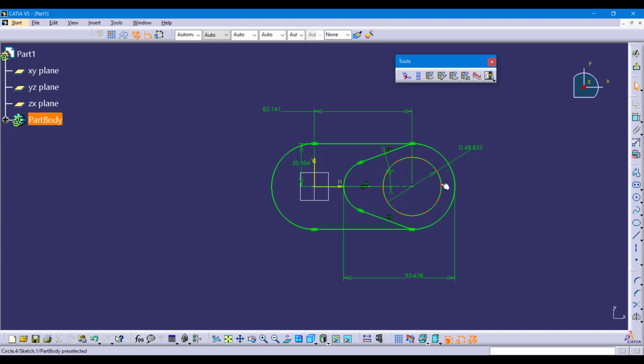The circle is a singular entity, and if you are trying to output or segment a singular entity, you are going to use the icon called Output Feature. Just simply click on the icon and then select your singular item. As soon as you do that, you will notice that that item does become thicker in nature.